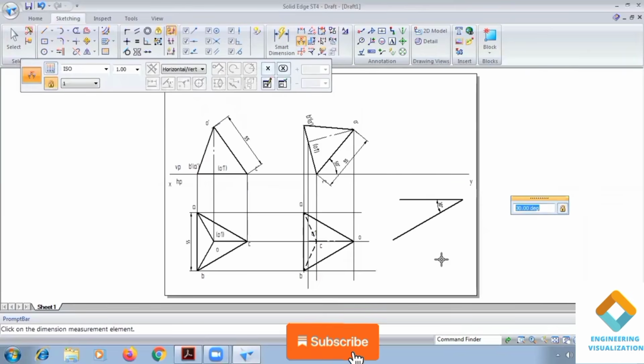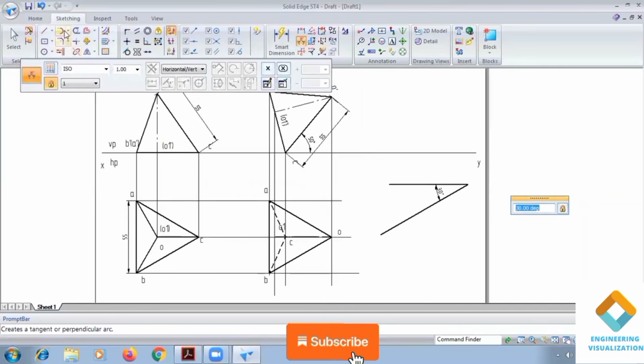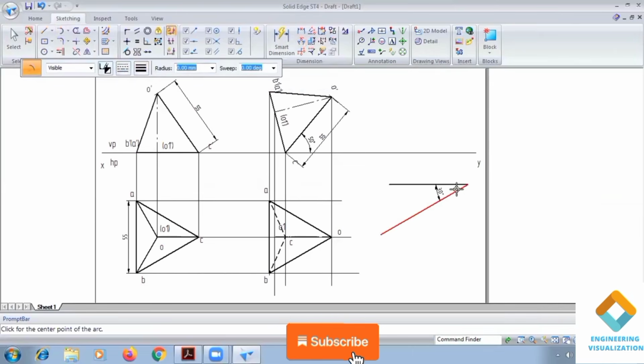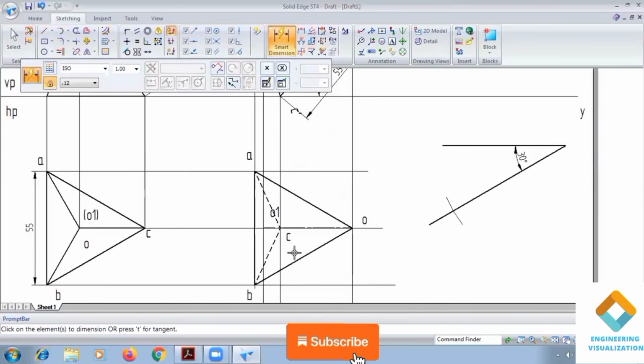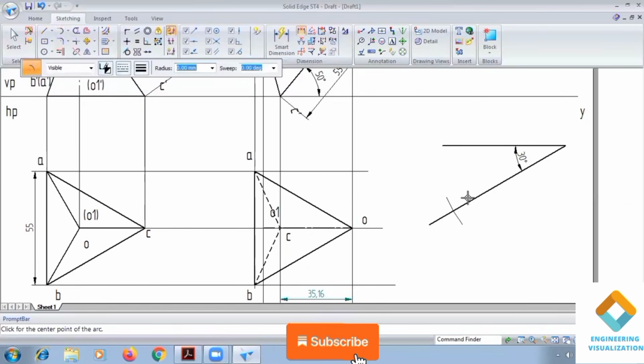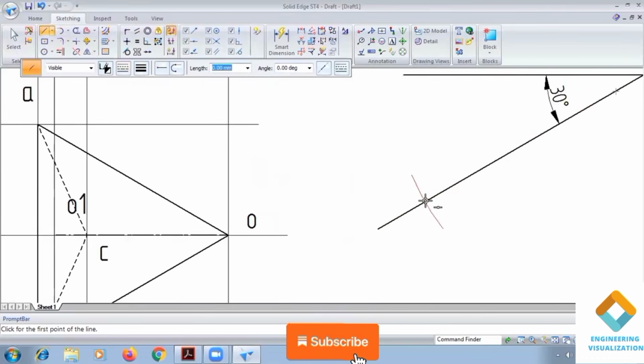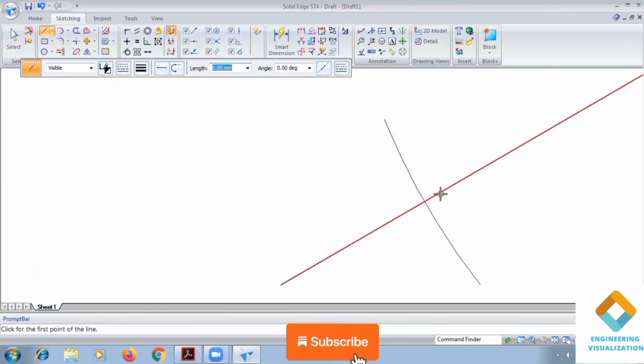Now here the slanted length you need to use, that is 55 mm. So go to arc by center. Take the 55 mm length and cut the arc. Okay, now draw the locus line. Another slanted length we have is 35.16. So these two lengths are required. One length we have already drawn. Now we need to draw a locus line here, a horizontal dashed line.